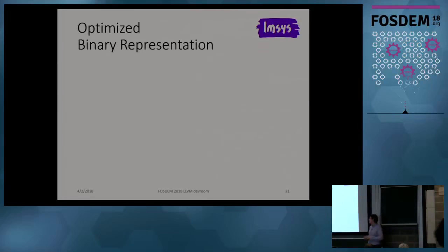Okay. And then optimizing binary representation. So the things on the previous slide already contribute to having a reduced binary size in the program memory. But also it's important to be clever when you design the binary encoding of an instruction set architecture. So we want to have a high code density, which means that a particular piece of software should consume as small program memory as possible.